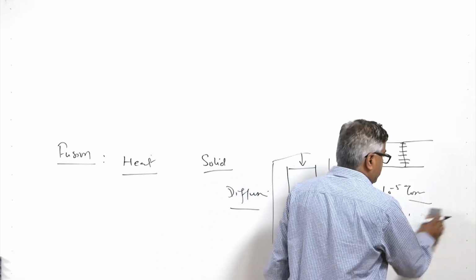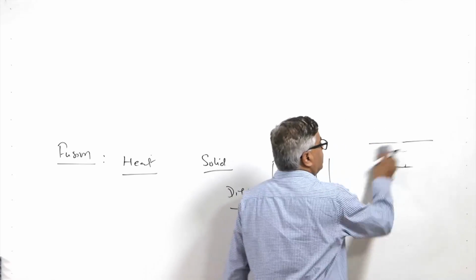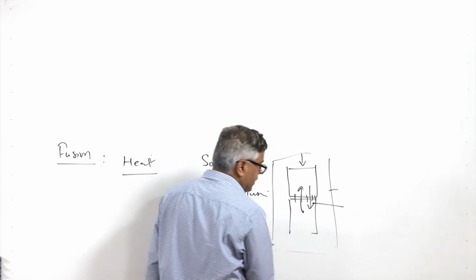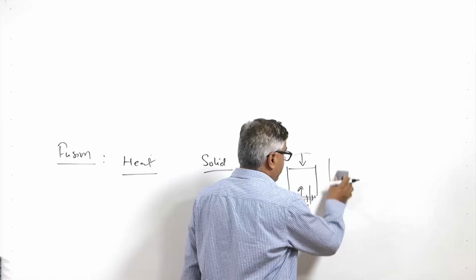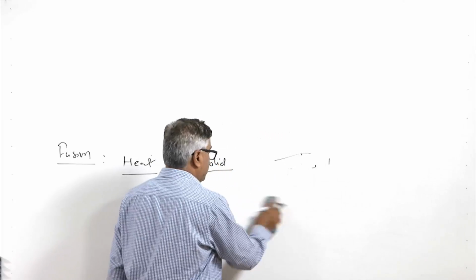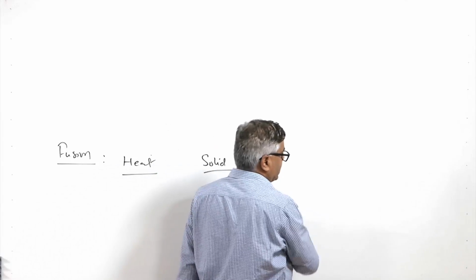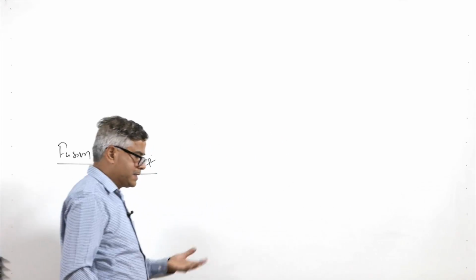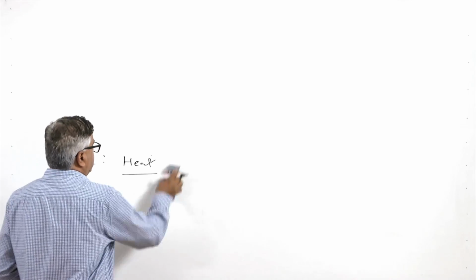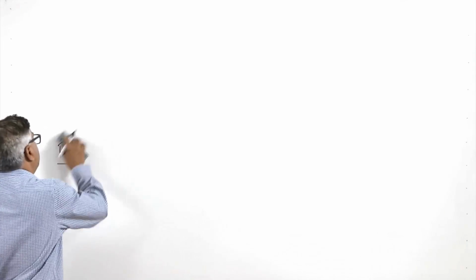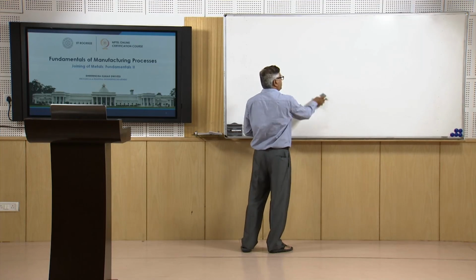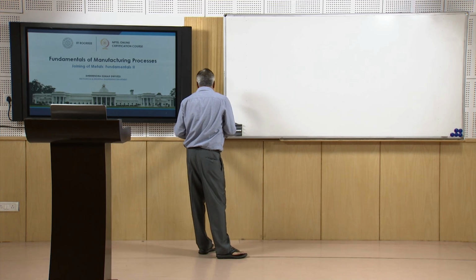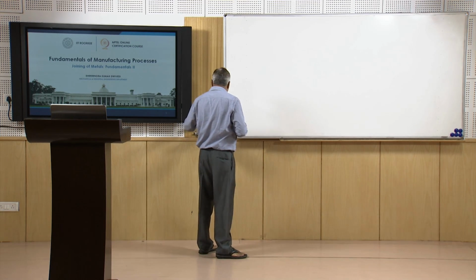Various approaches are being tried in order to increase the effectiveness of the diffusion bonding process through pressure pulsation or by putting in a soft material interlayer, so that the diffusion and the metallurgical connectivity, meaning the metal to metal contact, can be enhanced through the use of pressure pulsation, increasing the pressure, as well as the use of soft metal interlayers like copper, nickel, or silver, which are the common metal systems used for this purpose.